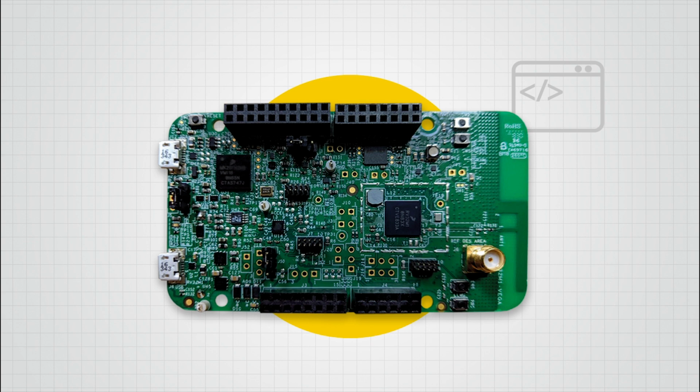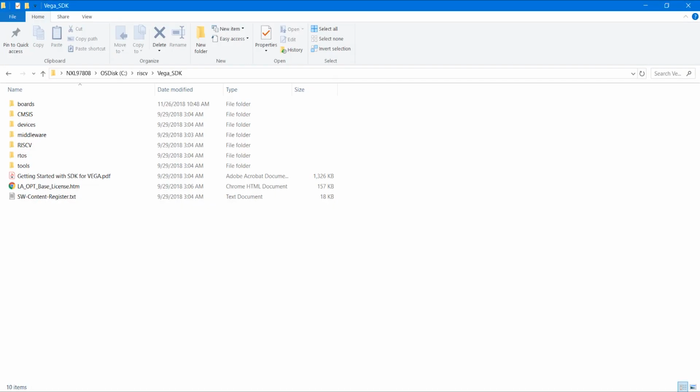The instructions are pretty similar to the Windows ones, so you shouldn't have any trouble following along if you're using any other operating system. First, we're going to be using GCC command line to compile the code, and then we will be using OpenOCD plus Telnet to flash it onto the board. And then we will use Eclipse to both compile the code and flash it onto the board.